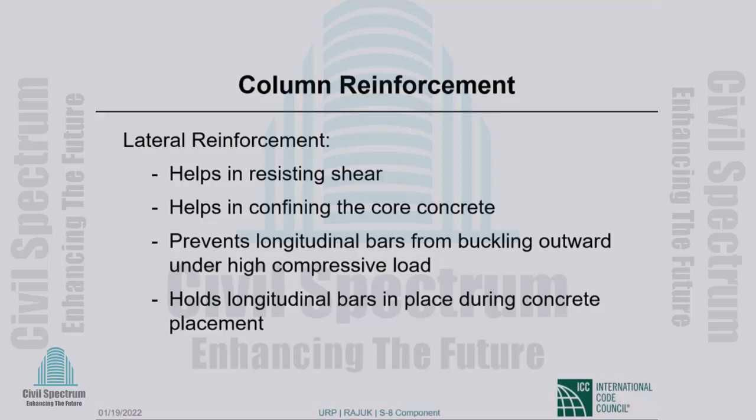It can keep on carrying gravity loads while deforming laterally by quite an amount. It doesn't disintegrate all that easily. It has ductility and toughness, all the properties that we will talk about when we go to seismic applications. So this confining role of lateral reinforcement is extremely important.